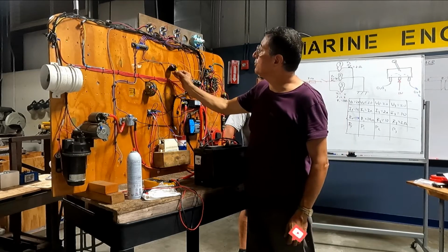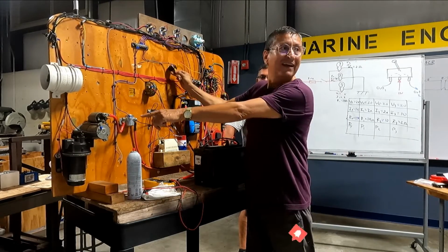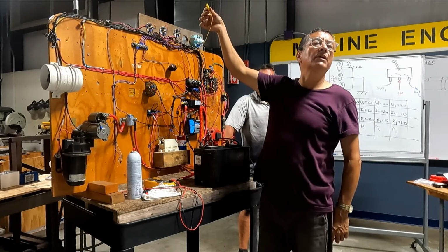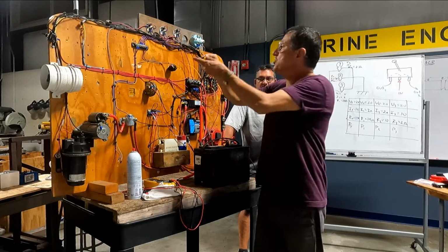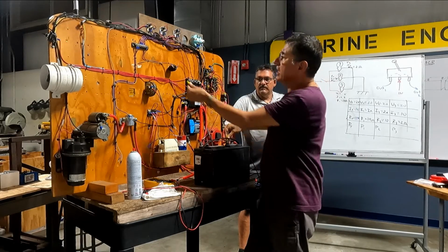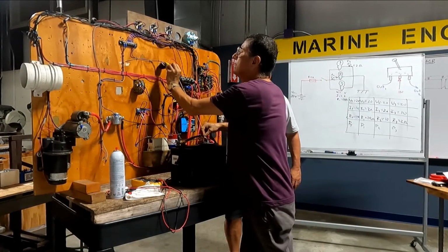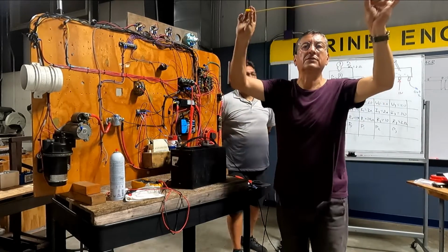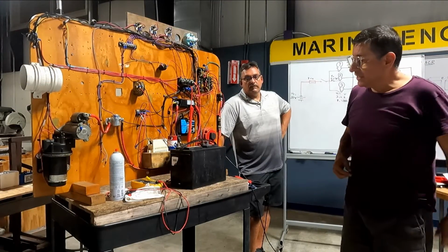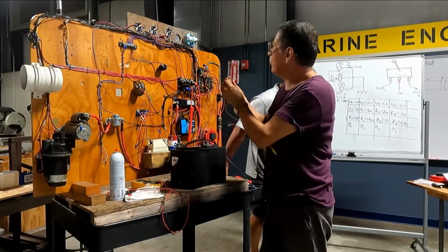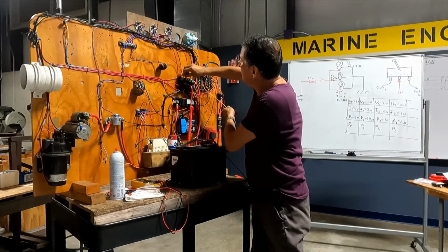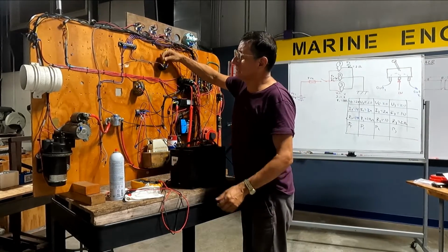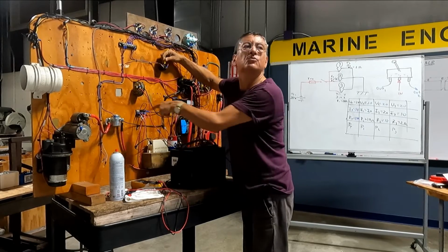Let me check the other position, start. I hear the click on the solenoid. I always need the jumper cables. Can I check directly from the battery? Yes, you check here and here. Okay, let me check for the click. I am going to bring positive to this one. It's this one, the click.